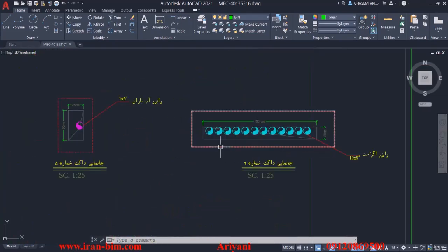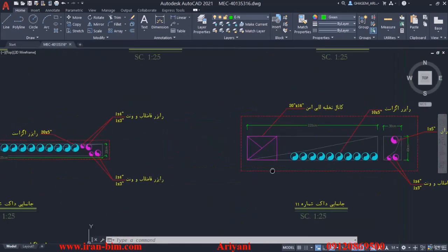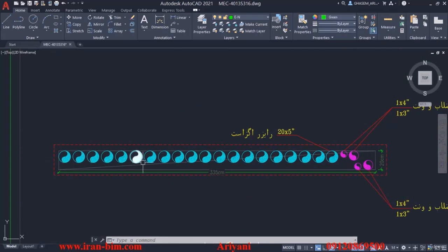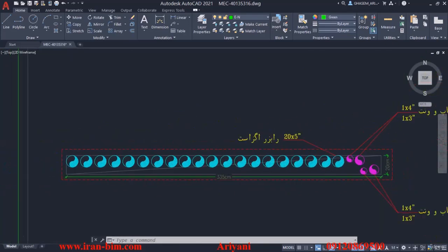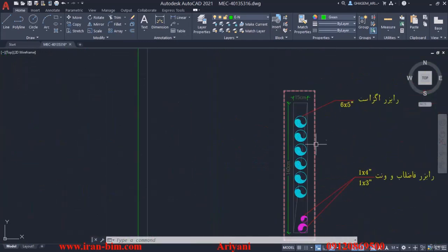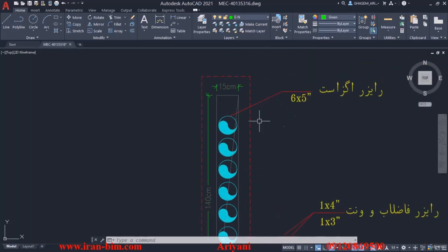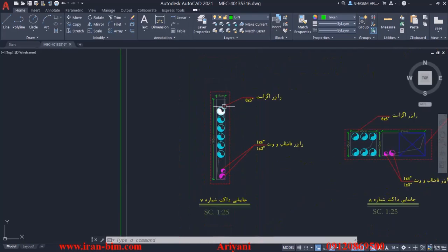Because in a lot of the cases in the AutoCAD file, we can go over here to see your example right here. So this is not actually possible or logical. They fitted the pipes cleanly in them like this, and it's because they just calculated the diameter of the pipes and then drawn. They haven't actually paid any attention to the area that the support needs. For example, look here. We have the specs, which are 15 by 140. However, this riser exhaust that we have here requires a support system behind it, something to hold up the pipe and the weight of it.